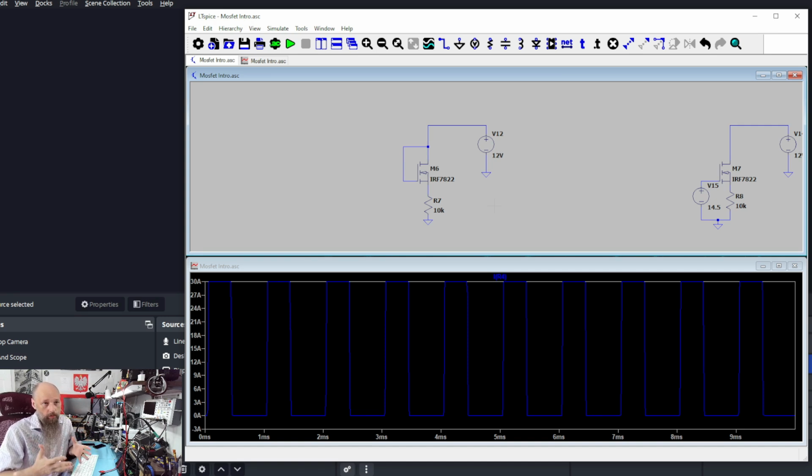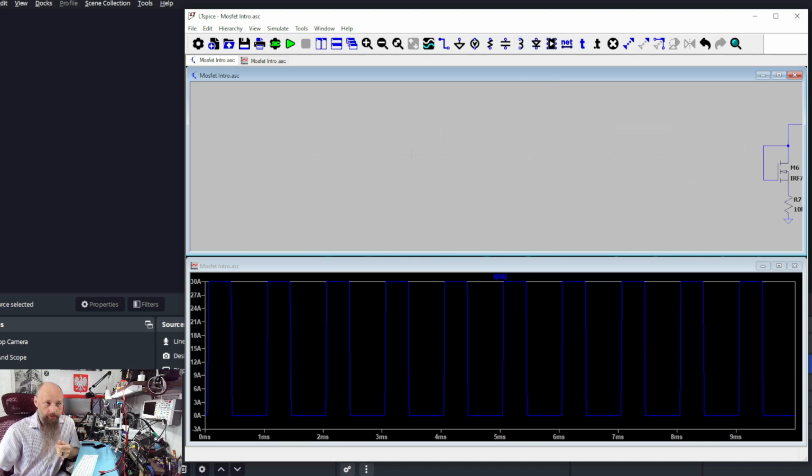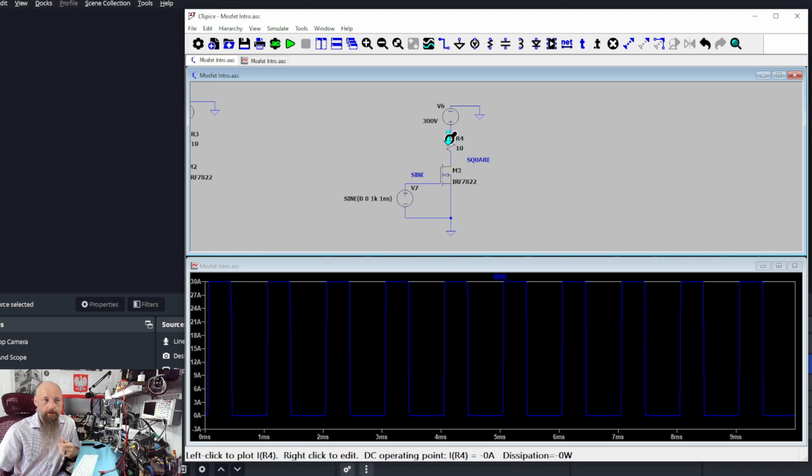So now to open the relay switch, we need to supply the voltage to the gate. Now the problem here is that when we open the transistor, the load is going to be on the source side, not on the drain side. So in our previous example, we open the transistor and the source is connected to the ground, while the drain is connected to the load.